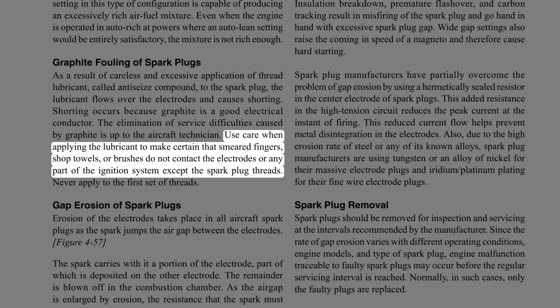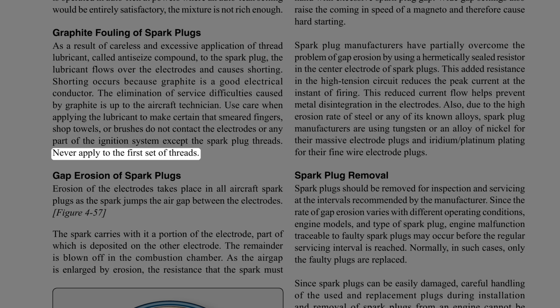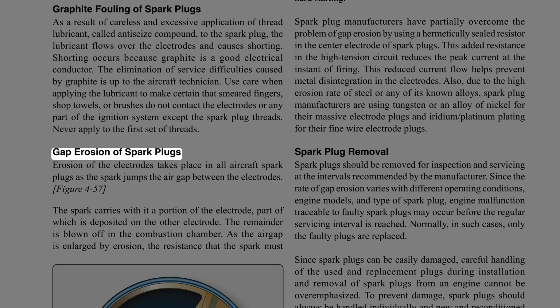Use care when applying the lubricant to make certain that smeared fingers, shop towels, or brushes do not contact the electrodes or any part of the ignition system except the spark plug threads. Never apply to the first set of threads. Gap erosion of spark plugs.